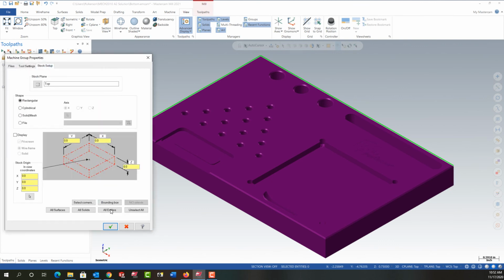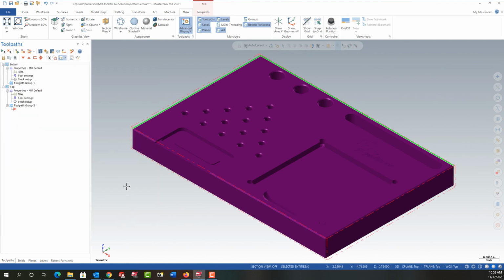I'm just going to use the bounding box again. So I'm going to tell it to grab all entities. I still haven't machined the part to length in the previous exercise. It'll be done in this. So here, once again, I'm going to add 1/8. But I have machined the top. So I'm only going to add the 1/32, and I'm going to come over here and add that to the Z as well. So it gets added on the top, and I'll say OK.